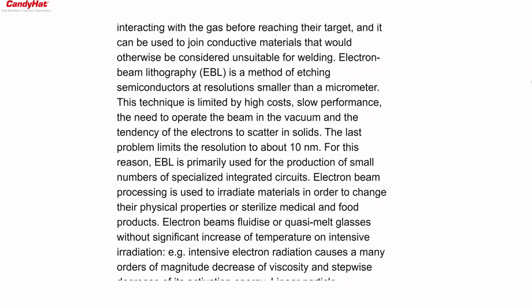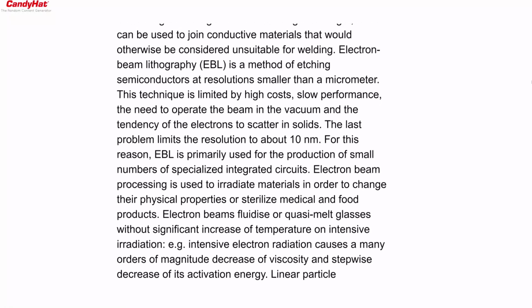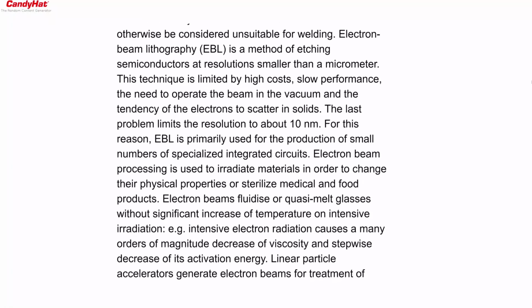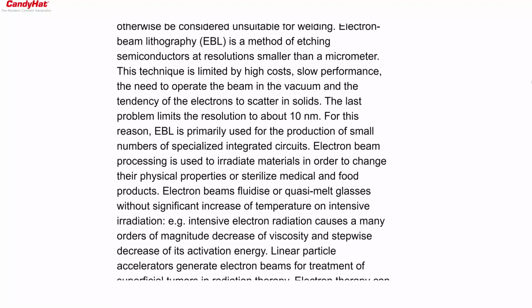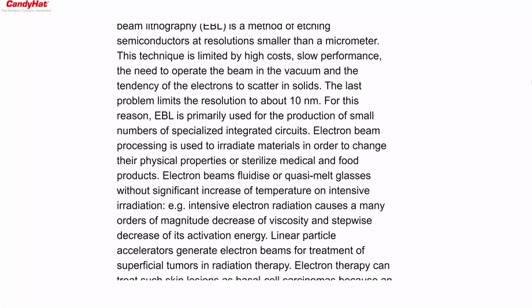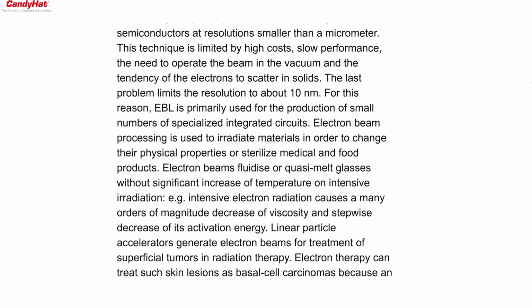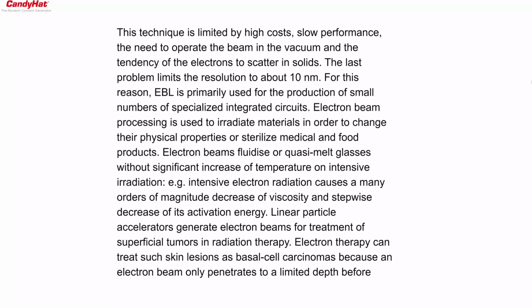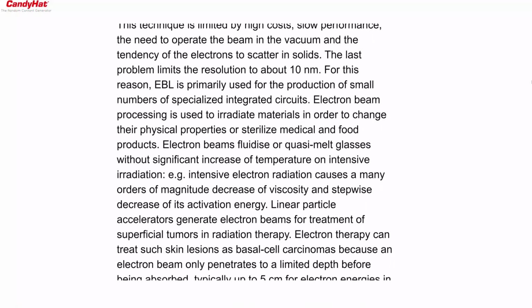This technique is limited by high costs, slow performance, the need to operate the beam in the vacuum, and the tendency of the electrons to scatter in solids. The last problem limits the resolution to about 10 nanometers. For this reason, EBL is primarily used for the production of small numbers of specialized integrated circuits.